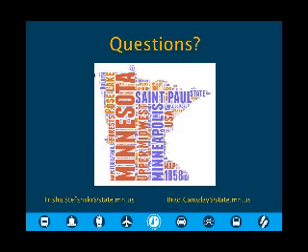Was some of the data collected using aerial LiDAR? And if so, which parts? No, not in anything that we presented. We do aerial mapping and get TIN models from that, and then if we scan a highway, we cut the TIN model from the scan part and paste it into the aerial data, so that we get a tighter roadway section for the designers.